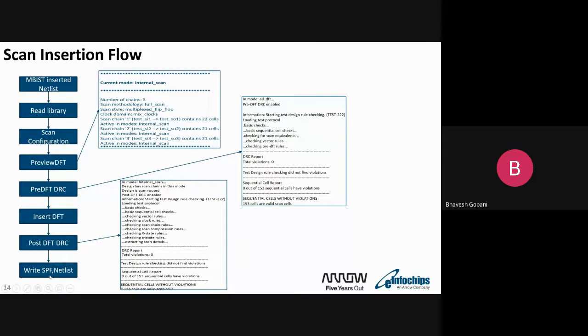SPF means it has a certain procedure to generate the faults and to target the design related info. I can say procedure file, Synopsys procedure file, in which certain information related to the DFT is included. So when I'm doing the ATPG, as an input, I need to take this file and this netlist as well in order to do the ATPG.